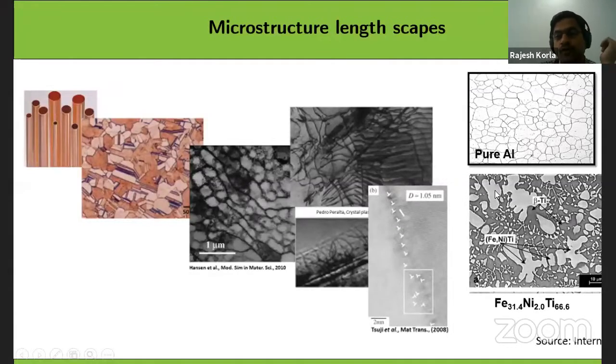So then you should know what the hardness is, what the modulus is, what the load displacement data is, if at all possible, of each individual phase. Then you can use that in the crystal plasticity model, and you can generate a much more representative macroscopic stress strain curve using crystal plasticity or FEM analysis, right? So all of this is very important, which is not possible in a conventional mechanical testing machine.